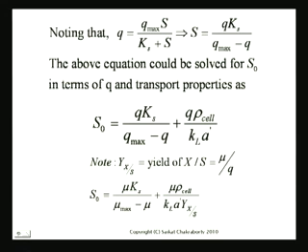So what happens is that when I wrote this equation, I used q because q was for the substrate, whereas when you use these notations, you have to remember: when you use it for the cell, it's mu, and when you use it for the substrate, it's q. Okay, and mu over q is the amount of cell produced, or amount of x produced per unit amount of s that comes in. Okay, is it clear?